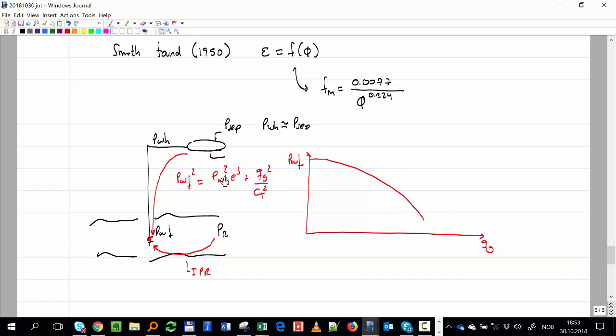Okay, I have wellhead pressure. The separator is making sure that I have always that pressure. The rate, that's the numbers that I'm going to change. And the CT, that's something that I estimate, right? And the S also. So then I can compute the pressure. Is that pressure available or required? Required, right? So it is the pressure required at the inlet of the tubing to be able to flow that rate against this wellhead pressure.